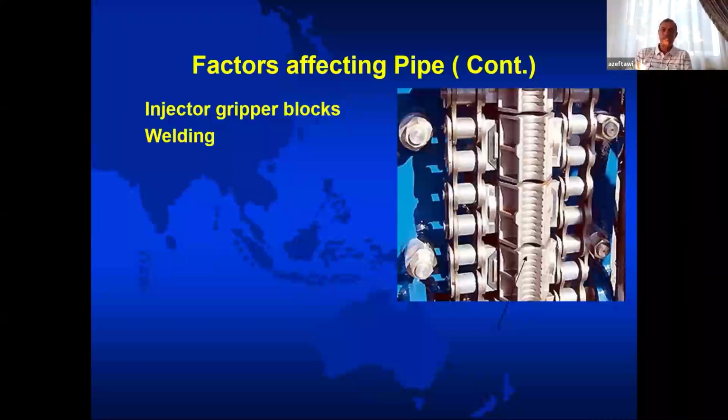So the pipe comes without any weld, but during the job, if you have a pinhole, then you take the pipe to the yard and cut this damaged part, and then you weld again. When you weld them again, this weld you create in the yard, we call it a butt weld. The butt weld is a very weak weld because it includes the filler material. This is number one. Number two, it creates around the weld what we call heat affected zone, where when you take a cross-sectional area around the pipe, all the cross-sectional area is affected.